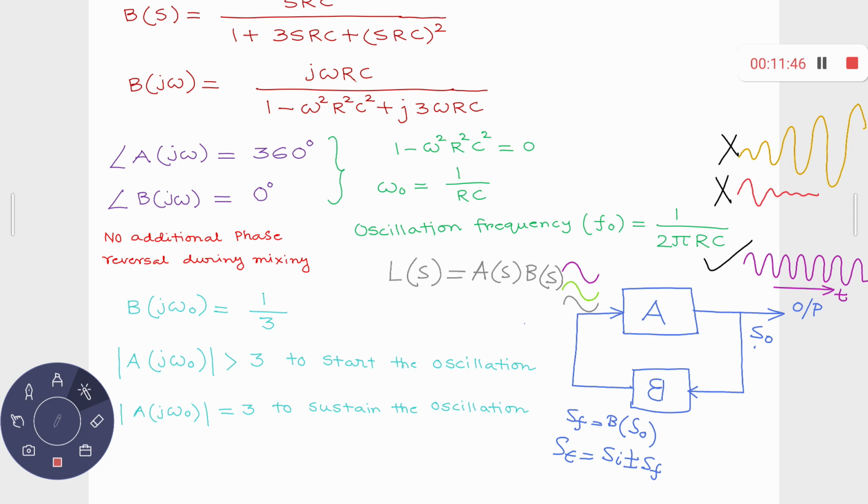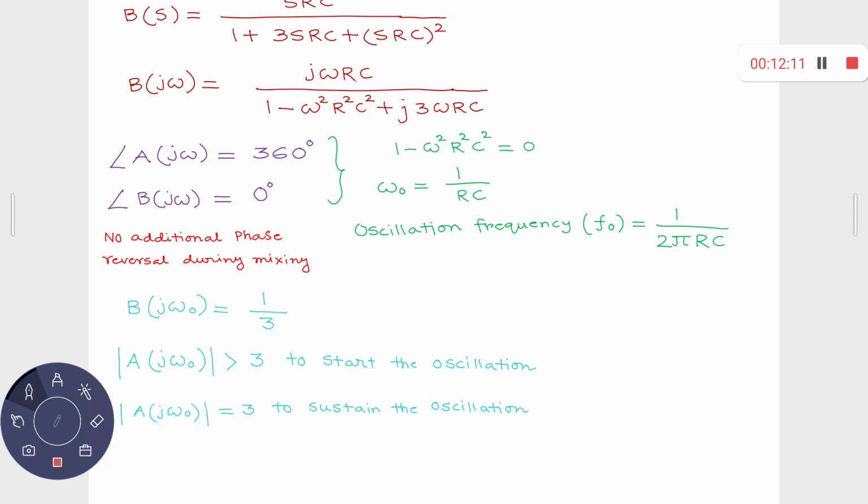Right? So the sinusoidal signal is known as a monotone signal because it consists of a single frequency. Now, since the Barkhausen condition is satisfied only for a single frequency, that's why it is known as a sinusoidal signal oscillator. That means it can generate the sinusoidal signal. You can call the Wien Bridge oscillator or the phase shift oscillator a monotone oscillator. But for a given value of R and C, these RC oscillators we discussed last day are meant for audio frequency generation.